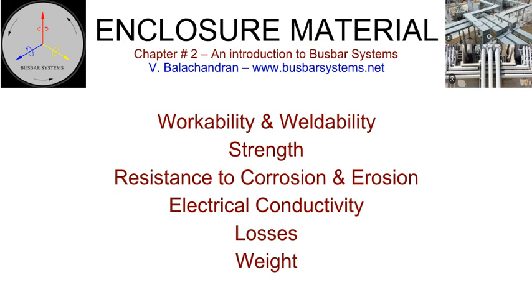Electrical conductivity. Enclosure material with a higher conductivity is advantageous as it will contain losses and act as an electromagnetic shield. In many designs, where the enclosure also serves as an earth conductor, higher conductivity is preferable. Enclosures of isolated phase bus carry a current almost equal to that of the conductor, and to limit the losses and temperature rise, they are fabricated from high conductivity aluminium.